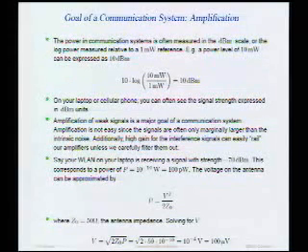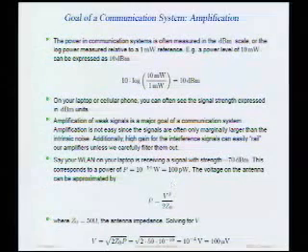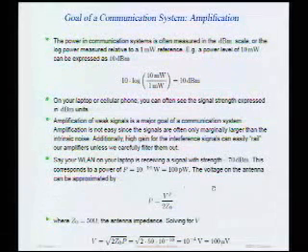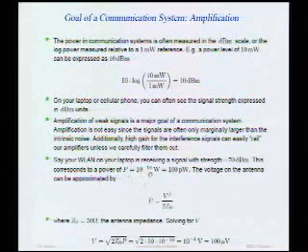It's good to know that because almost all the communication equipment that you carry around with you has a little signal strength indicator, which is an estimate of how strong the incoming signal is. If you look at your wireless LAN, you might find that a typical signal strength is, say, minus 70 dBm. Translating minus 70 dBm into watts, that's 10 to the minus 10 watts, or 100 picowatts. It's not much power, is it?